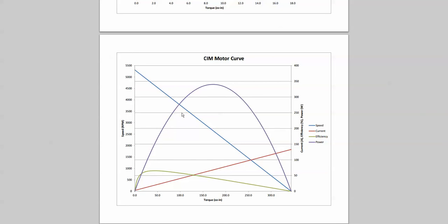The farther you go to the right, the lower your duty cycle must be, as in you must run that motor less per match at that operating point, or you're going to overheat it and fail it. Some teams really like to push that limit. We end up doing that a lot, to where we often might be replacing motors every event, and some people might think that's crazy.